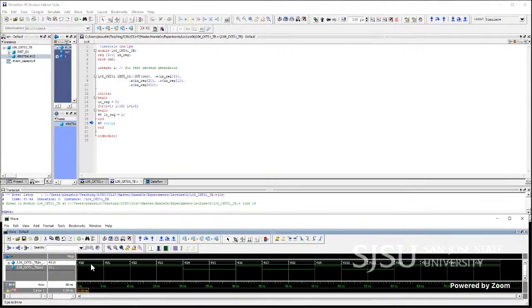So look at this logic functionality now. If it is 0, then my output is 1. If it is 1, output is 1. So far, so good according to our spec. So anything less than or equal to 3 would be 1, right? 2 is 1, 3 is 1. And anything greater than or equal to 12 would be 1. So 13 would be 1, 14, 1, 15, 1. Anything divisible by 3 would be 1. So 12 is divisible by 3, 9 is divisible by 3, 6 is divisible by 3. So they are at 1. And we have zeros for the other logic combinations. So it seems like this circuit is working okay.